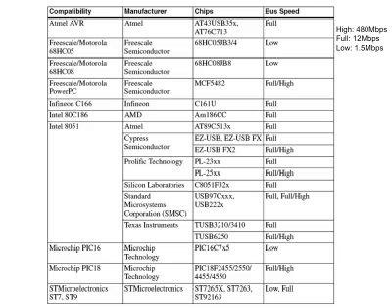Here's a table that gives you some examples. For example, from Atmel, it has chips that support full USB speed. And you have Intel's microcontrollers here that support full speed or high speed. Microchip has this PIC18F4550. This is a very popular USB controller that you can use, and there are source code examples that you can leverage to speed up the design.